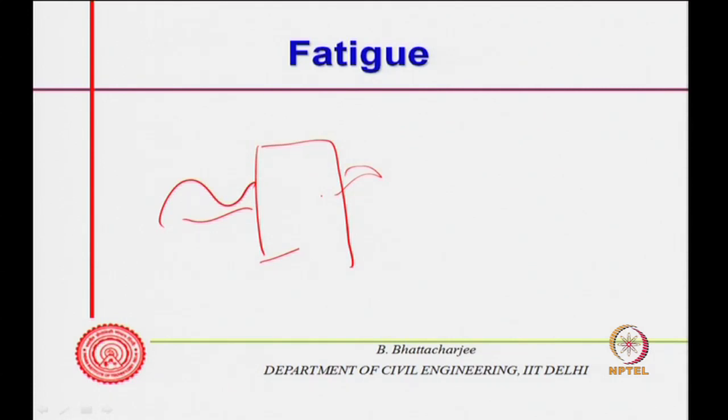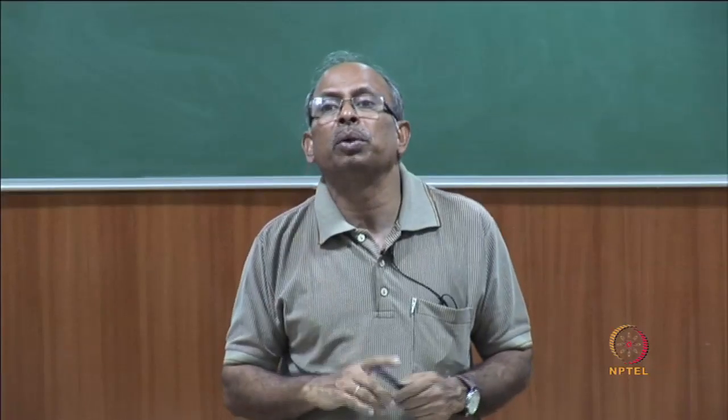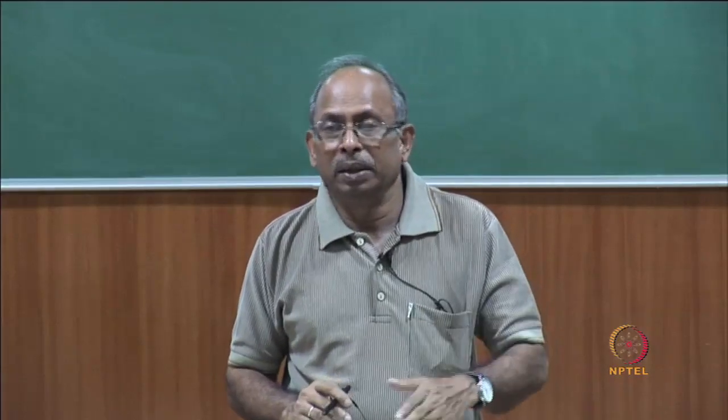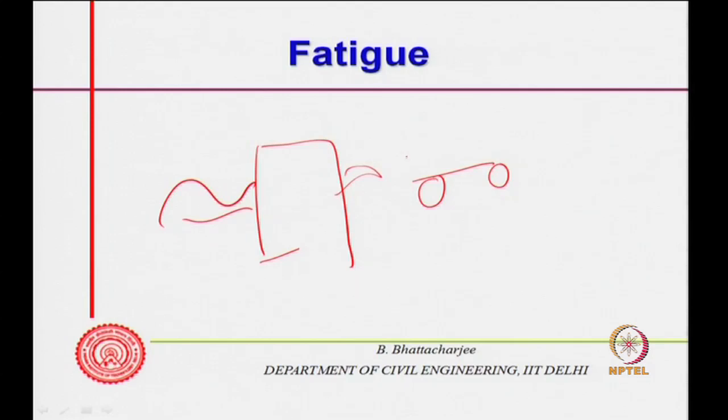It is then under a reversal of stresses. On bridges, a vehicular load comes onto the bridge deck, and then it moves on. So there is a reversal of stresses onto the deck.